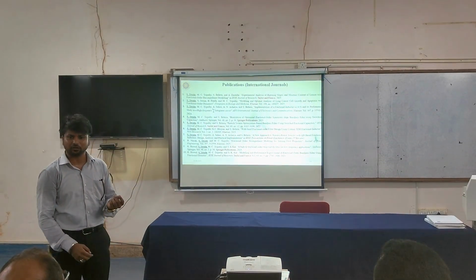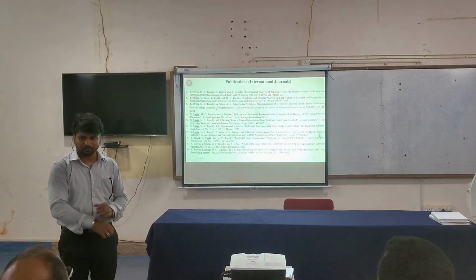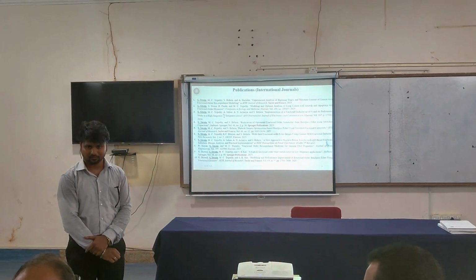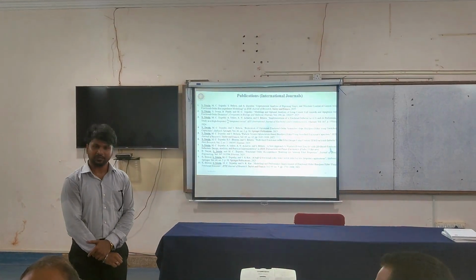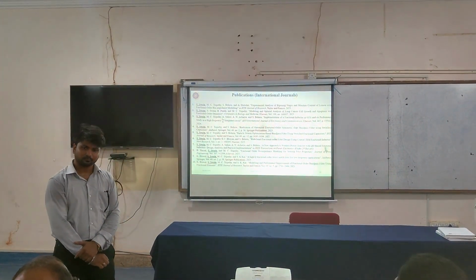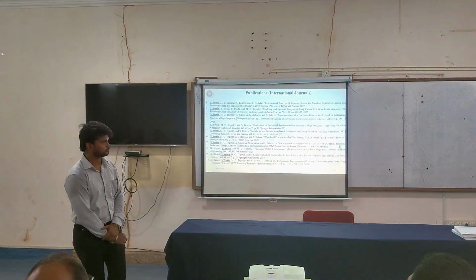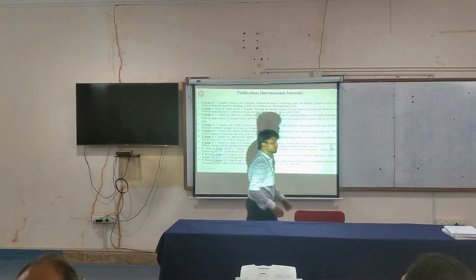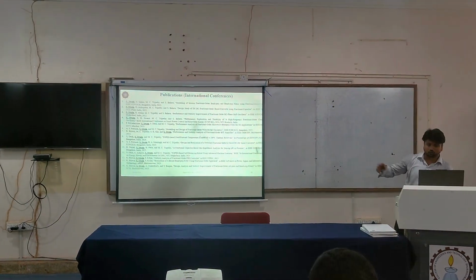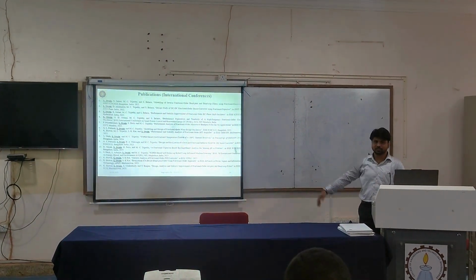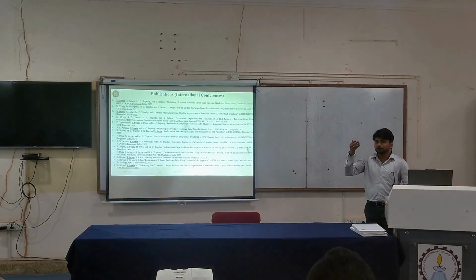You have the material, the experimental fractional-order inductor and capacitor. You conducted experiments today, and after 3 months or 6 months, with the same material and the same device, you get a slight change in the phase as well as a drop in magnitude. Since it is ethanol, some part evaporates, because we are making a prototype.